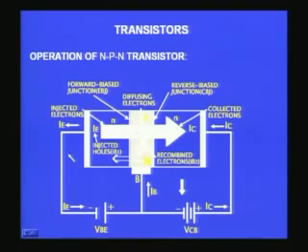The first region is a low resistance region, and the next region, which is the collector base region, is a high resistance region with a reverse bias junction. Therefore I am able to push almost the same amount of electrons through a low resistance junction into a region which automatically passes on to a high resistance region. Therefore I am able to push a large current through a large resistance on the collector base junction, and the product of large current into large resistance is large voltage.